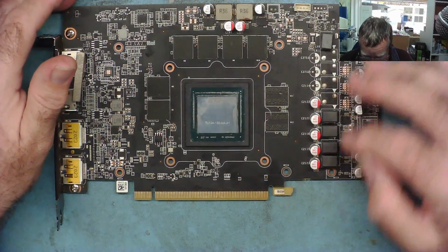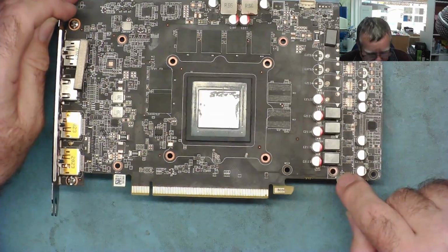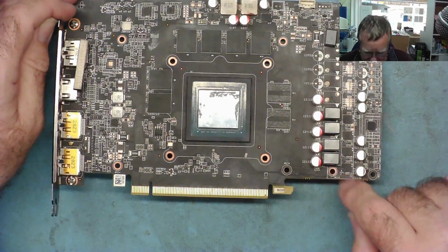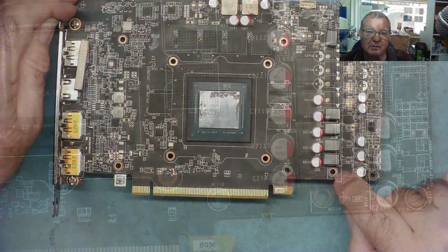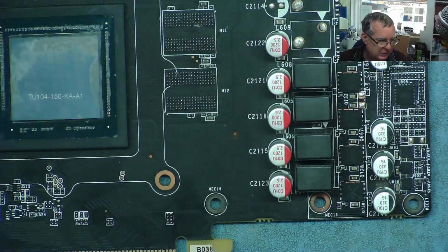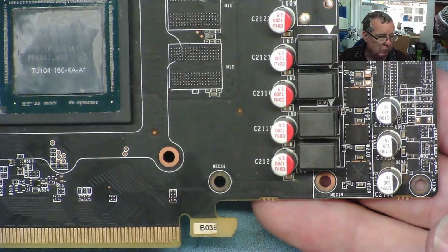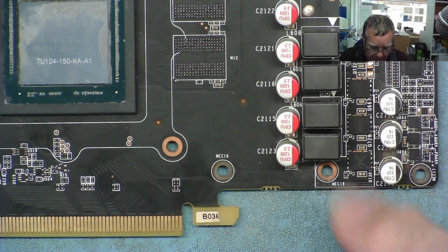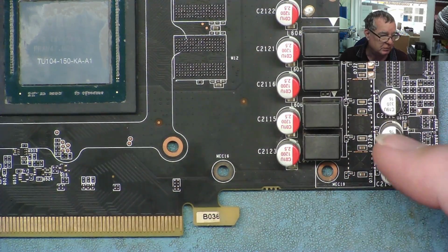Having said that, now we know this is the short circuit device, we're going to have to remove this because it needs replacing. So I'll show you now how I actually go about removing one of these. The first trick about removing these is to use the preheater, which I'm going to use. So we need to get a lot of heat in from under the board, such that when we come to use the hot air on the top, we don't need to heat it up so much.